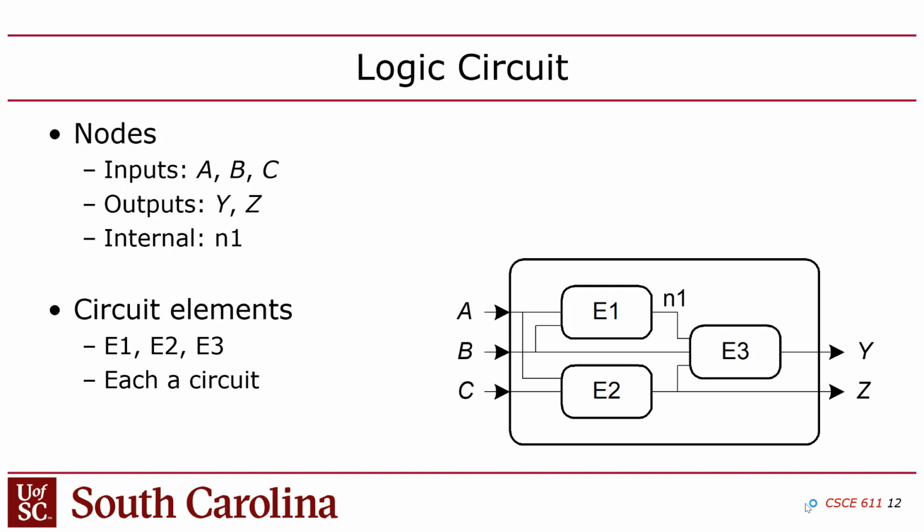So you're writing a module, and then inside that module you instance 3 modules. You create a little block diagram, and then you connect the inputs of the module to the inputs of the internal modules, and then one of the internal modules has an output that connects to the top level output, to the Y, and then there's another one, this output here connects to Z.